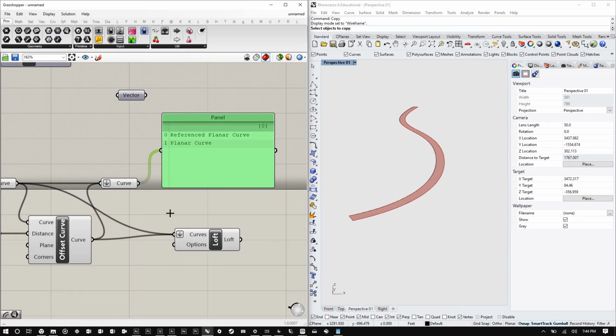So we'll probably run into a point where this matters in terms of editing, but actually, we've run into that point now. In order for the loft command to work, it needs to see all of the curves in one tree. It didn't work originally because they were in a grafted state, and it was seeing just 1 curve twice instead of 2 curves once. So that's why it wasn't working.